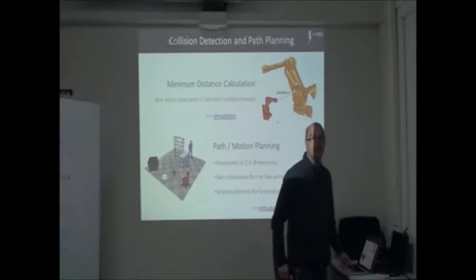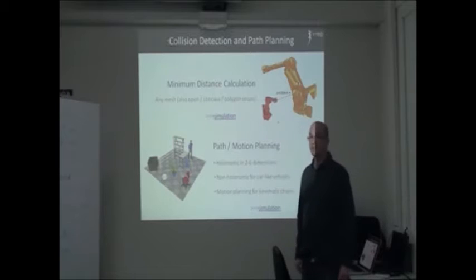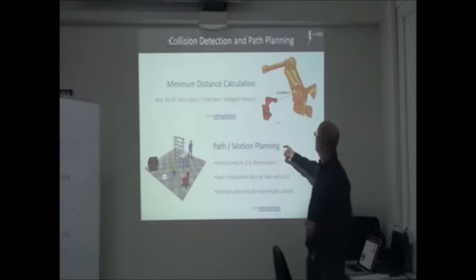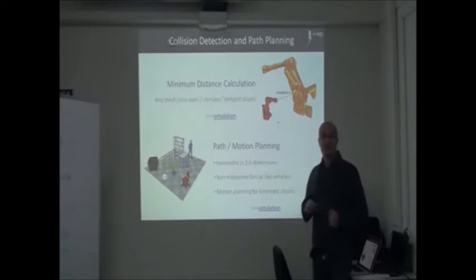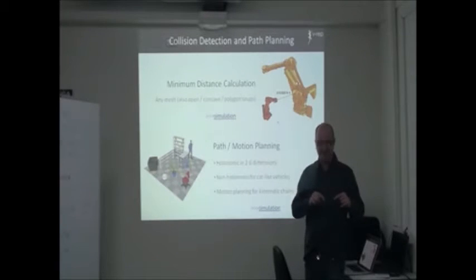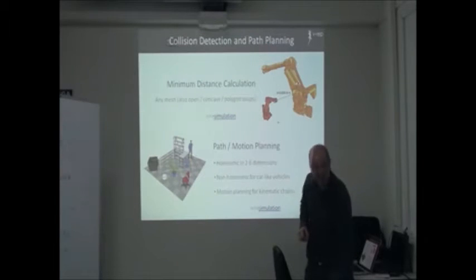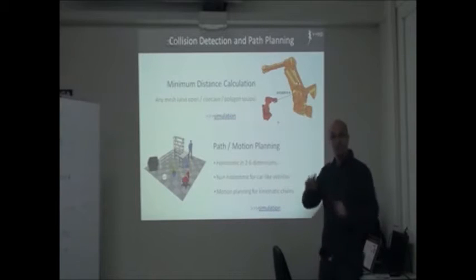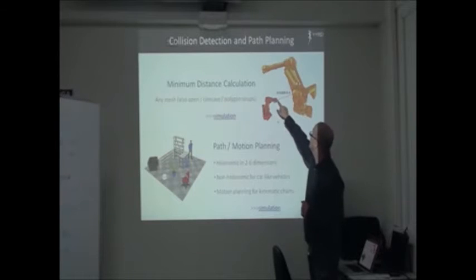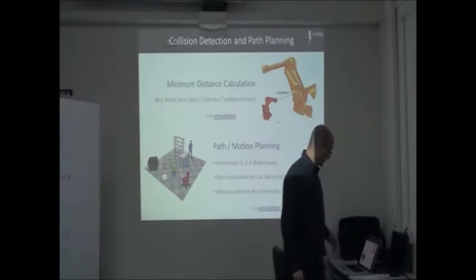You also have an algorithm, the minimum distance calculation. This is to know what is the distance between two objects. It's mesh to mesh. For instance, the distance between me and you, how to measure it? That would be maybe my knees up to your elbow, some point from here to here. That would be the minimum distance. So VREP has this kind of calculation algorithm implemented, from the mesh of this model to the mesh of this model. The closest one will be detected very quickly.